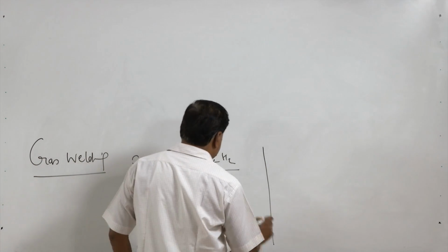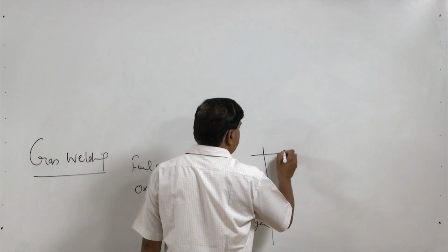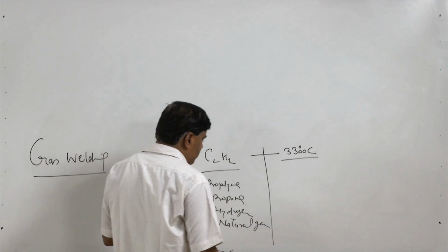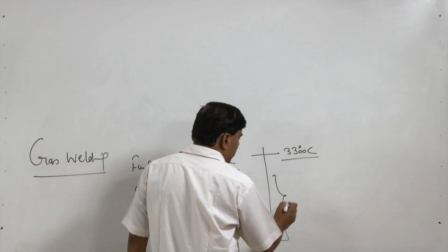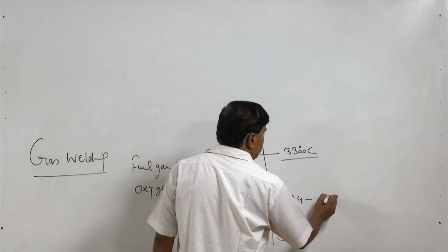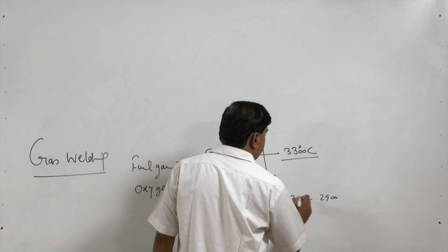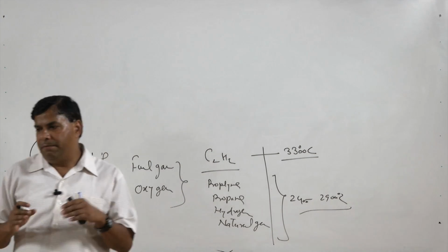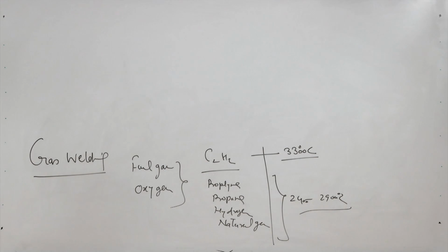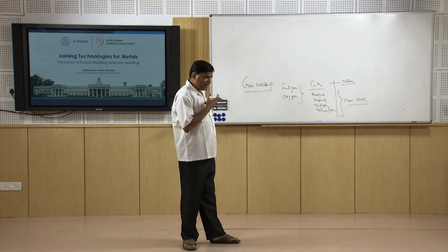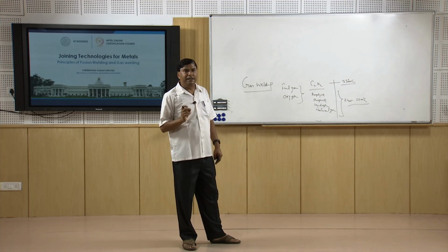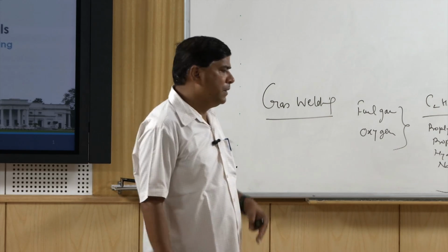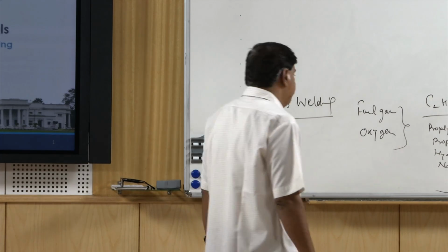However, the most commonly used gas is acetylene, because it produces the highest flame temperature, while the temperature observed in case of the other gases may vary, say 2400 to 2900 degree centigrade, and this lower temperature adversely affects the performance of the process, in the sense that it takes long to start the welding, because it should reach the flash point, or it takes really long to start the process and thereafter the welding.